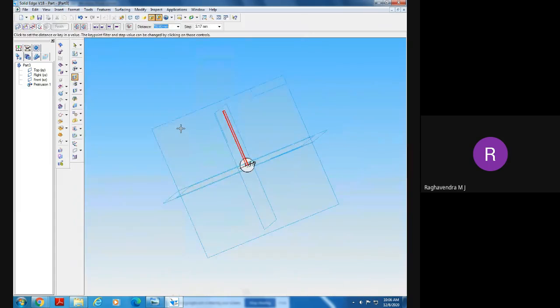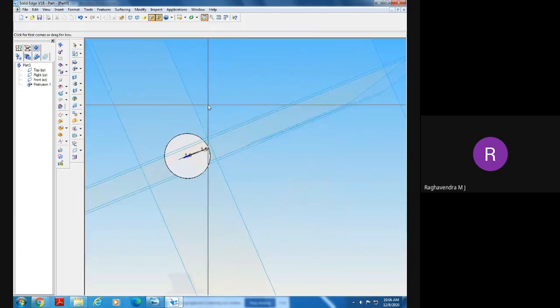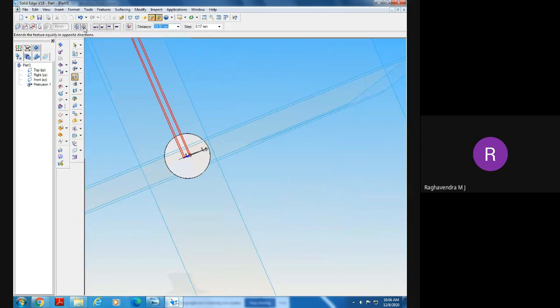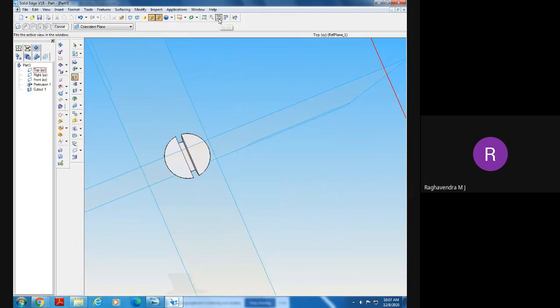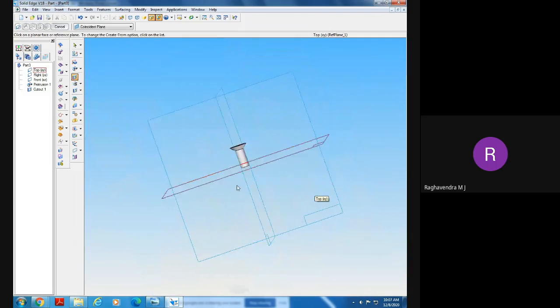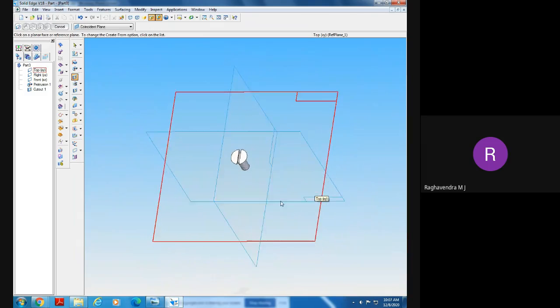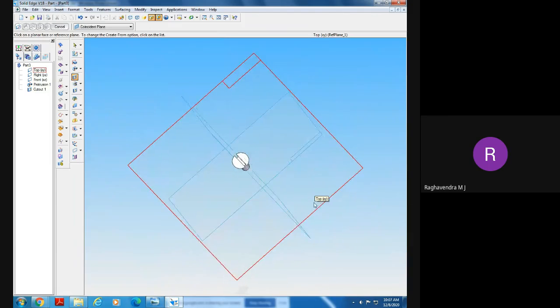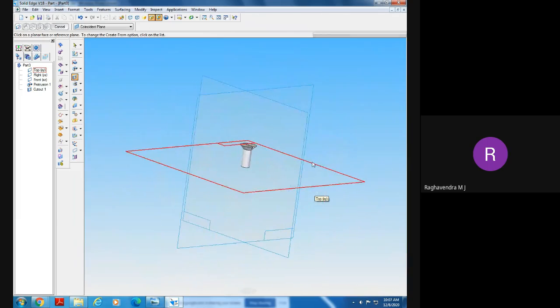Now click on the return option. Which side do we need to cut here? Both sides or one side? Both sides we need. Click on symmetric extent. Place it. Finish it off. Are you able to see this here? That cutout. What is the use of this cutout?